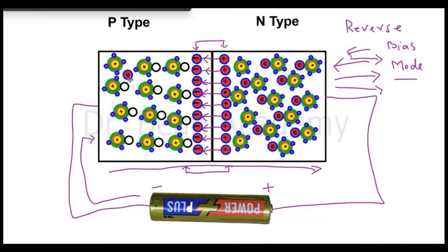So there might be some free electrons available on the p-type side, although most of the stuff is present with the holes. When the p-n diodes are made, you can consider it like a manufacturing defect. Just consider it like that. And if those electrons are available here, for example, this electron's situation is the same as the case of forward bias mode, because now here we have a negative side. So this electron will feel the push towards the right side, I mean towards the barrier.